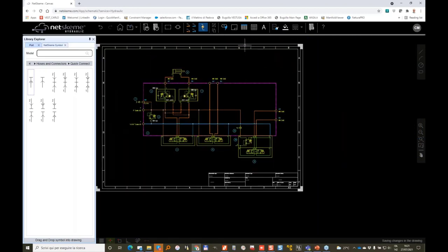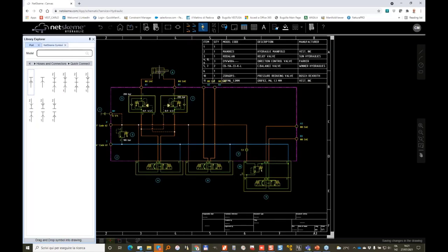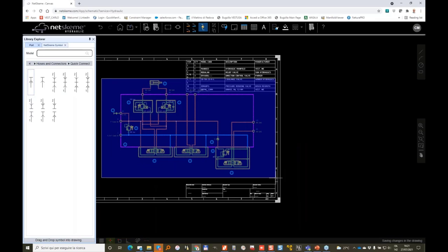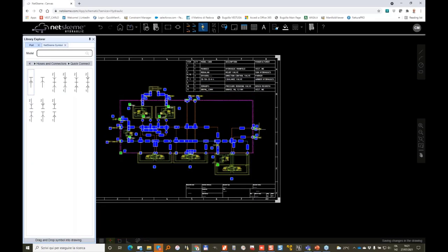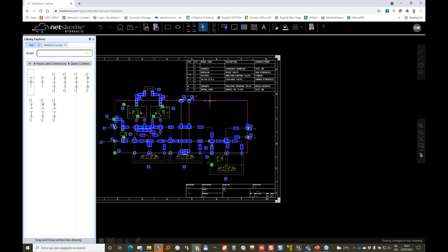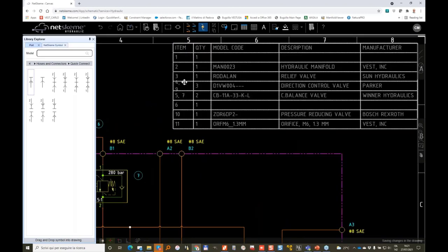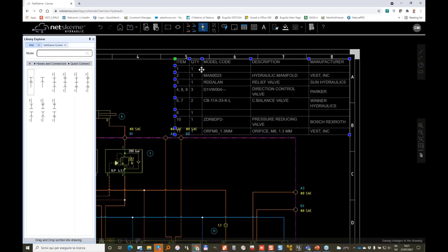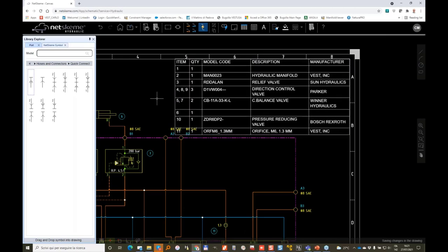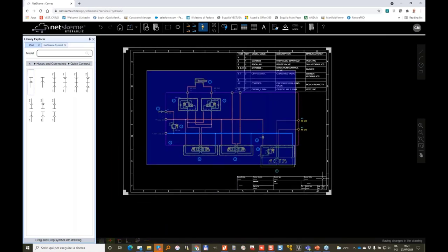And we can make a part list by using this command, insert part list, that will create our part list and will group identical items. Let's move it a bit to the diagram. You can select and move the whole diagram just using arrow keys. I see a small problem here. If you see the part list is not fitting properly, just select a row and extend the line. This will make it work fine.